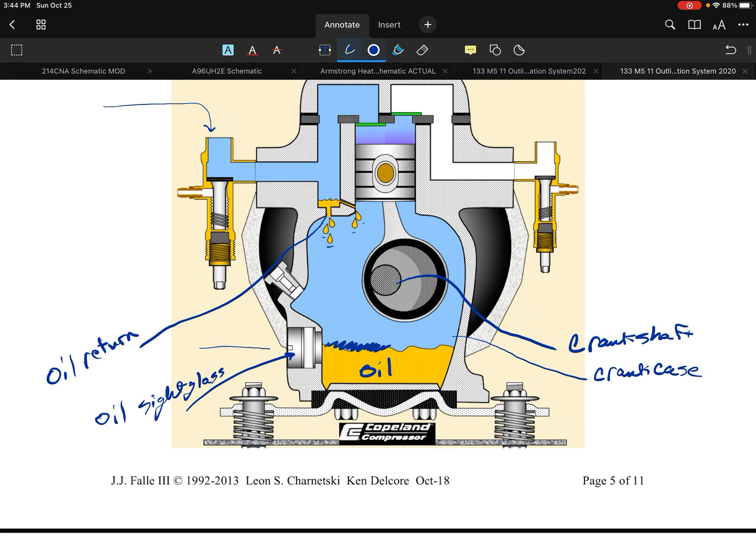We hope the oil will be dense enough and heavy enough that it'll drop into this little cavity, which is right in this area. And this little cavity should allow the refrigerant to flow right down into the crankcase. And that should indeed happen. Of course, it's very much needed because you've got to be able to lubricate the pistons and the cylinder walls and those things. So oil return is pretty important.